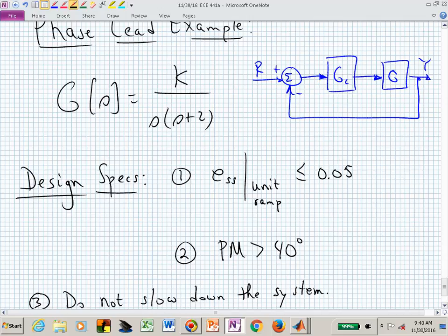Do you see the classic root locus? You start at the origin and -2, and those come together. They break right at -1, and they just go up as you increase the gain k. This particular system has an infinite gain margin.